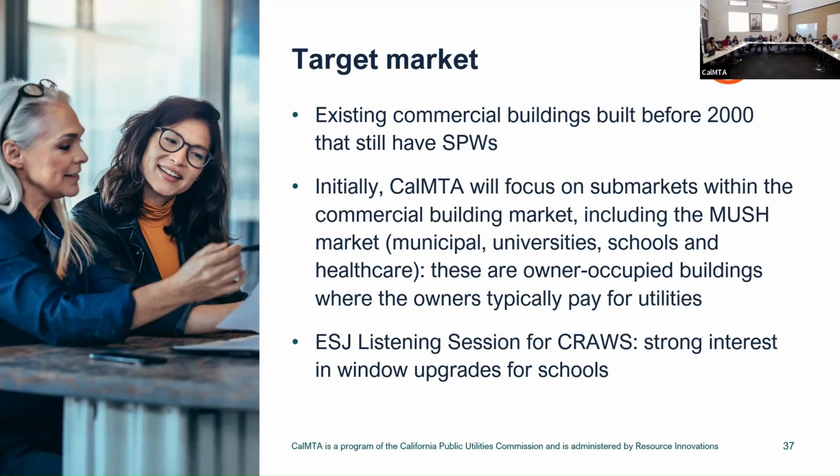There are secondary windows that are operable. The issue you get into there, especially if you're doing modeling and trying to forecast savings, is you have to model if you want to operate that exterior window. There can be really good reasons to do that, and there are actually energy savings. If it's cool outside, pre-cooling the building just by opening windows and letting in fresh air in the morning can be beneficial from an energy perspective. But it gets a lot more complicated to figure out what human behavior is with the operability. Will it stay up or down?